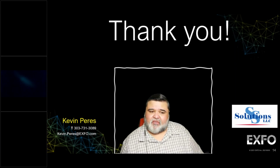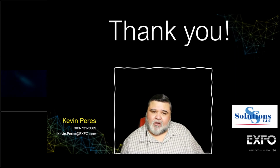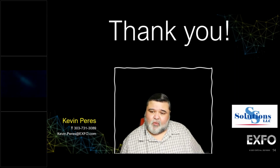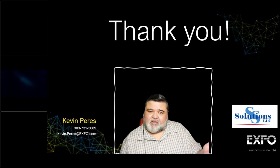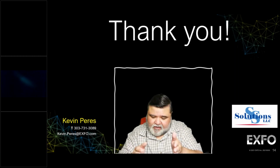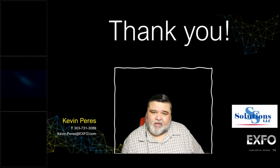I can get you a list of all the thresholds. The thresholds that we have set are based on the thresholds that are expected for those types of percentage splits. So we know exactly what the loss should be for a 99-1, right? Because it's really based on the incident power of the IOLM or the source versus what comes out the other end, right? Just standard loss testing. And so we do have those values, and that's something we can get you.